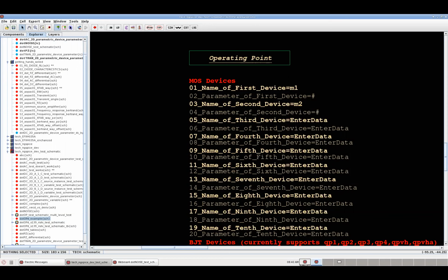But my circuit takes time to settle to a certain operating point, then I want to do AC analysis around this operating point. So how could we do that? In HSPICE or in Eldo, we do something like .op at some time. We define some time for the circuit to take the operating point at that time, and then solve AC analysis around this operating point.